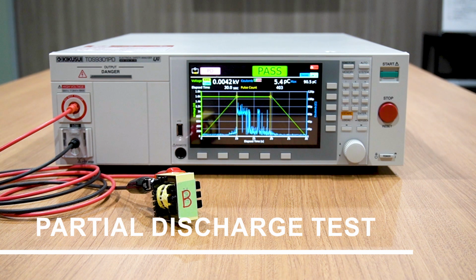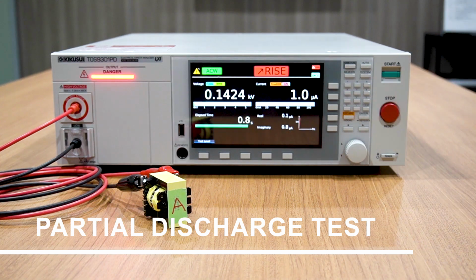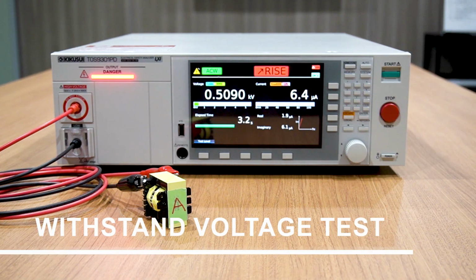Next, let's see what happens when the withstand voltage test is performed on these two samples. First, we'll perform the withstand voltage test on the good transformer, which is sample A. The test conditions are the same as before and 1600 volts is applied. As you can see, we measured a small current value of 23 to 24 microamps, resulting in a pass. We know the product is good, and it is a normal result.